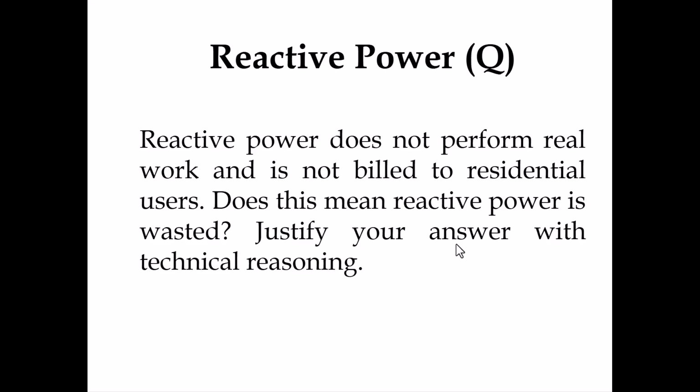Reactive power does not result in net energy transfer to the load. Instead, it is cyclically exchanged between the source and the reactive components of the system. In an inductive load such as motors or transformers, reactive power is used to maintain the magnetic field. In a capacitive load, it supports the charging and discharging of the electric field. Now, reactive power does not perform real work and it is not billed to residential users.